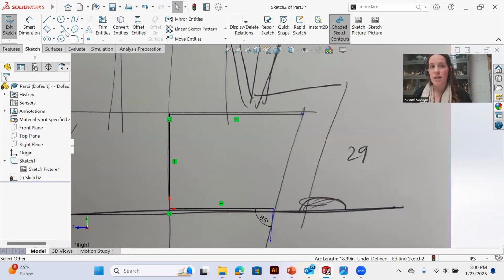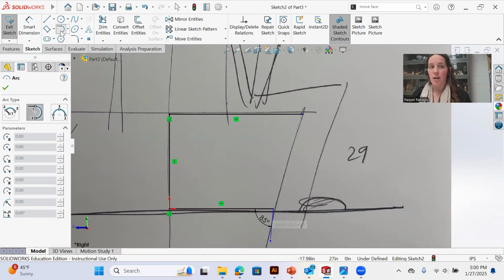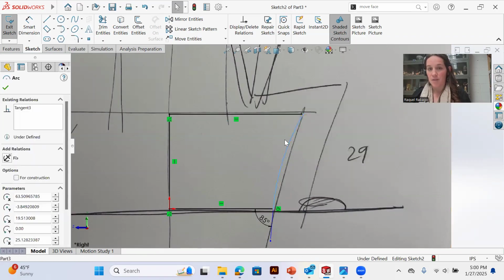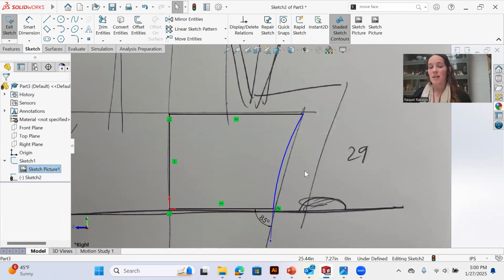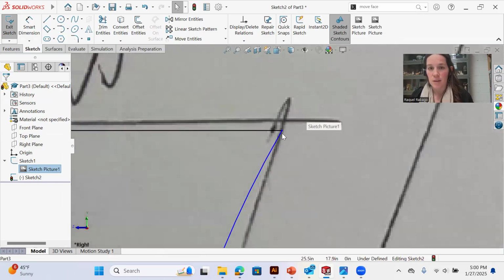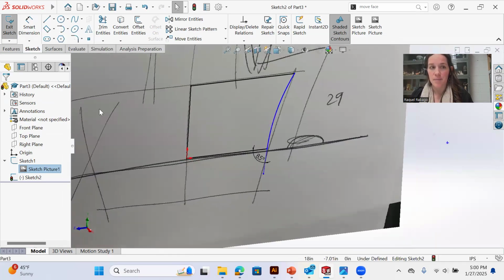it's a little more free flowing, but you can also do an arc. So tangent arc would be tangent to this, and then whatever the resulting curvature would be up at the top. You don't have any spline controls, but what that does mean is a nice clean curve. It's a singular curve. It doesn't have any points where it is inflecting or deflecting to another direction. So when I'm building in solids, that's a really nice way. If you know you're going to keep it simple for now, just use that tangent arc tool. So see that.